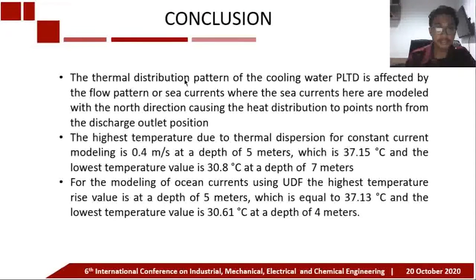The first is that the thermal distribution pattern of the cooling water of PLTD is affected by the flow pattern or sea currents, where the sea currents here are modeled with the north direction, causing the heat distribution to point north from the discharge outlet position.